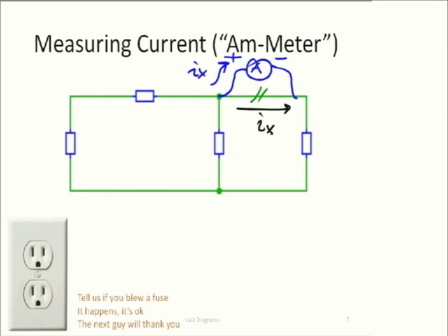So those are little tubes of glass, so you can actually look through them, and you will see a wire in there. And depending on the rating of the fuse, it could be rated for 100 milliamps, 1 amp, 10 amps, 5 amps, whatever, you will find that the wire is actually thicker or thinner. In fact, if you go to any car part shop, you can go and look for the fuses. You will see these little glass tubes that contain these wires inside the glass, and depending on the rating, they're going to be wider or less wide, and then there are some metal prongs on either side. So those are the very simplest fuses.